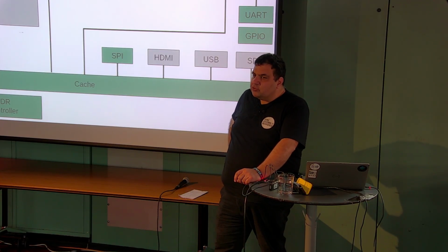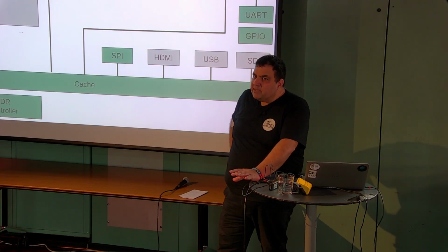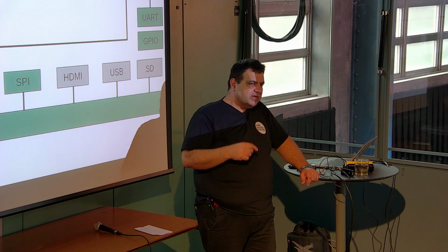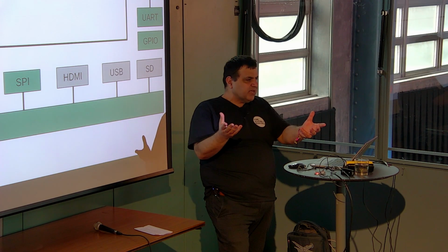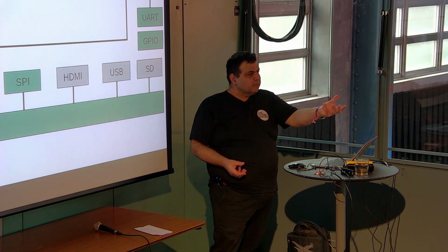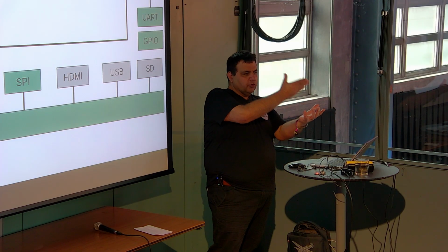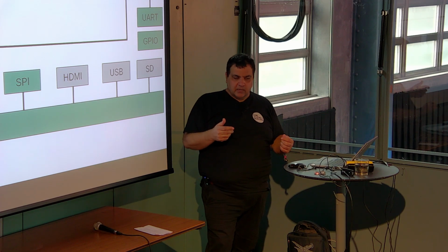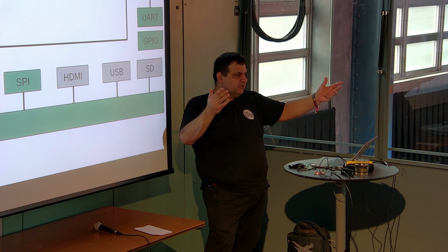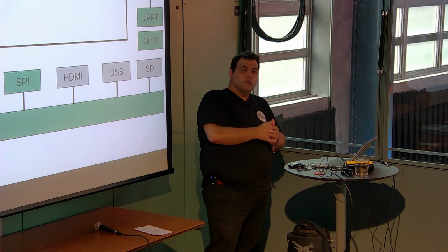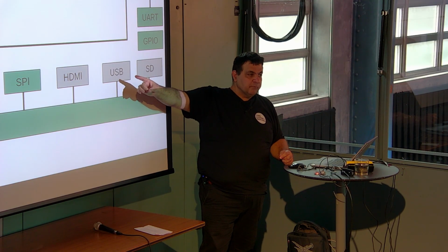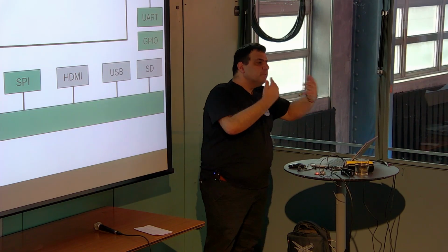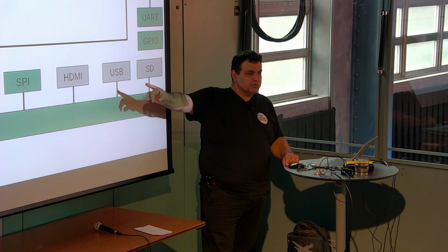The hybrid approach you're offering wouldn't work at all, for the same reason I'm not using an FPGA like the MiSTer. The MiSTer has an FPGA that has a built-in ARM core in it. So it has an ARM core that loads Linux and an FPGA. And it allows it to do things like put up a menu and then have that menu select which core you load, which this will not be able to do. It will be able to reprogram the flash so that after a reboot it will be a different core, but it will not be able to switch cores on the fly.